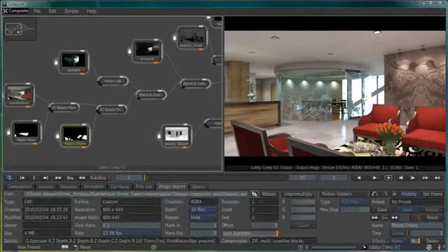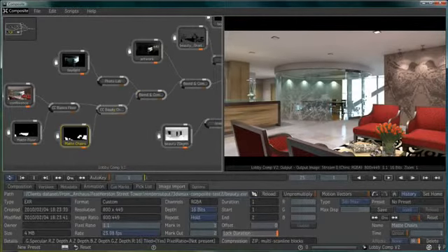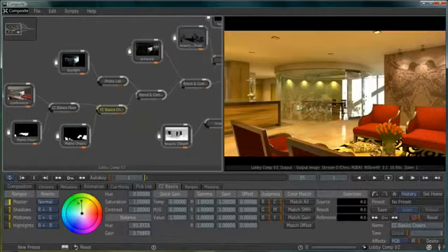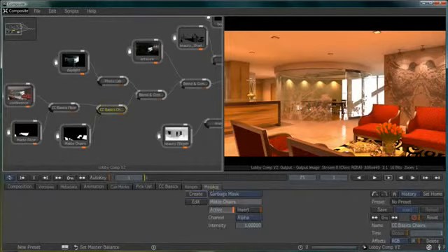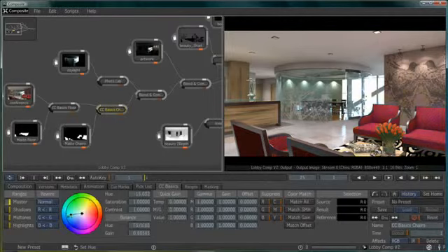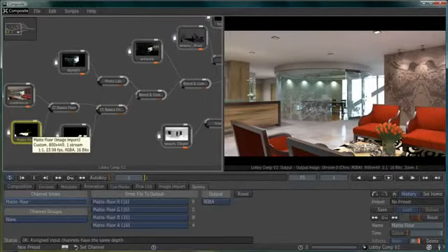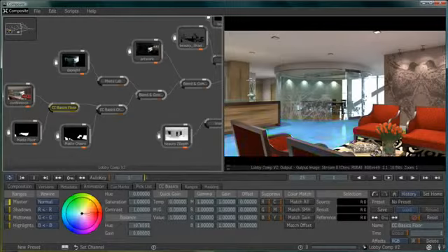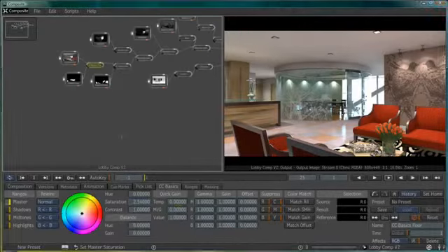While using my chair matte, I can do color changes on the red fabric of the chair and look at different color options. You can do color changes on the entire image or select one of the RGB channels, forcing the matte to be used as a mask and perform the color changes on the chair fabric. I can also do the same color adjustment with any matte I have set for my scene, and I do have one for the floor. I will saturate the floor a little bit more to get more color variation on my stone tiles.